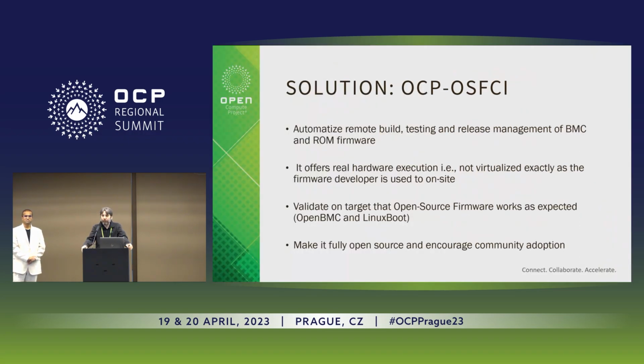So how can we automate firmware development, including node recovery and node breaking, and getting feedback just through a web page, and ideally from an iPad? Can I develop firmware directly from an iPad on my couch in the US or not? So what we have done is we started to tweak the hardware. That's the main benefit of working at HPE. We have motherboard engineers, and we started to remove the permanent storage, the SPI flash, and replace that with FPGAs. Like that, we can emulate the SPI flash on the systems.